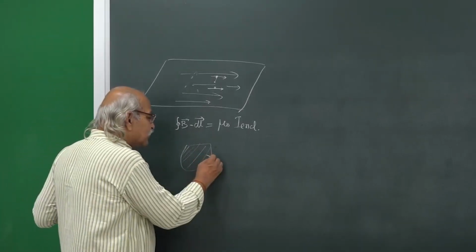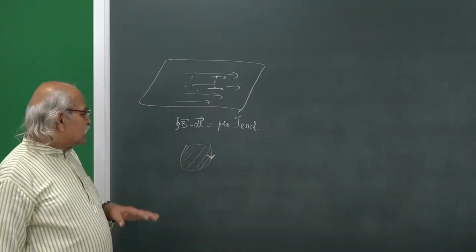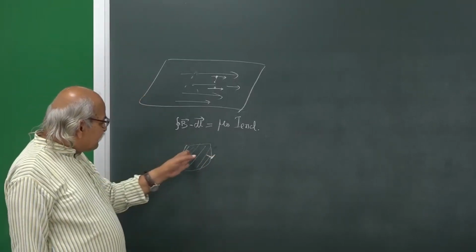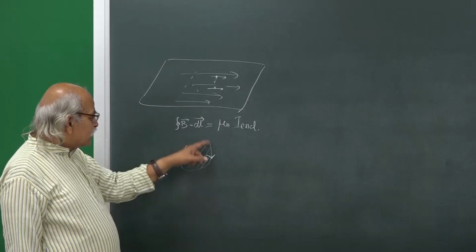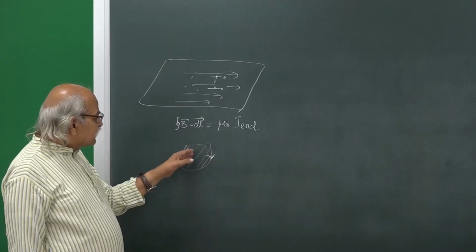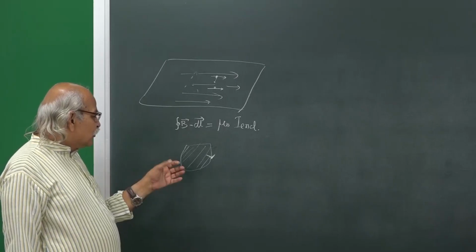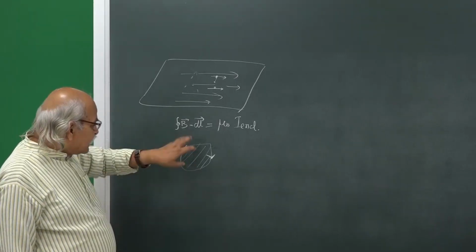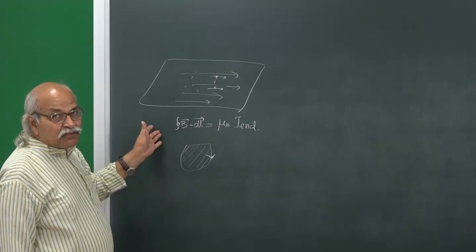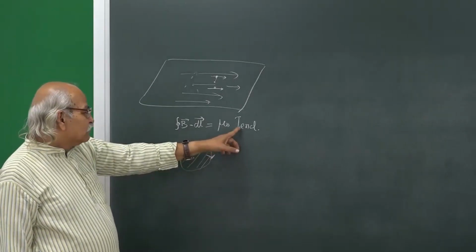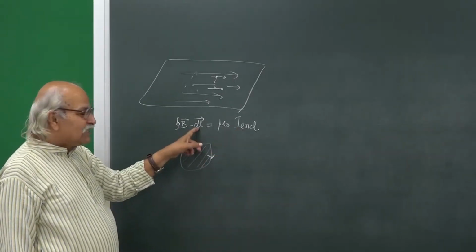The way I have put the arrow now, your positive direction will be away from you because it is clockwise. So, the positive direction is behind the board. How much current is going from our side of the board to the other side has to be written here, because that also decides the sign of this quantity.